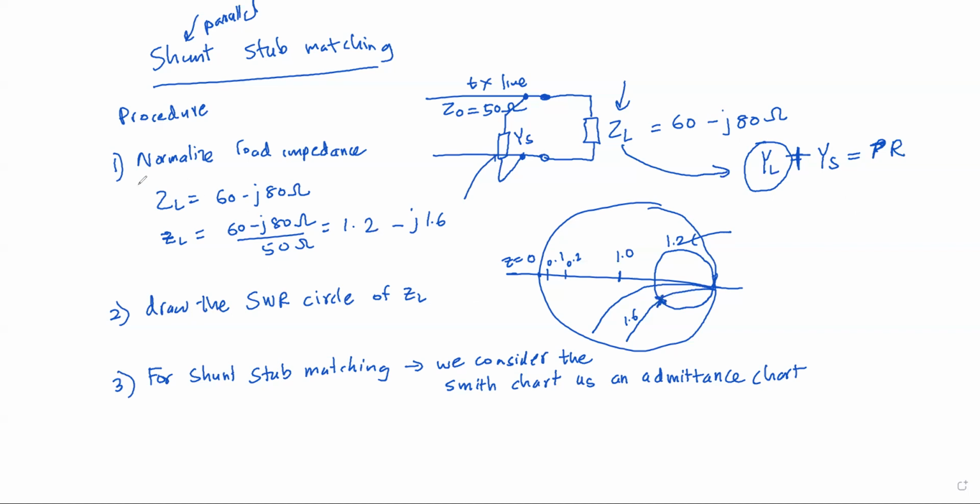So in the first step, you found the impedance value and you marked the impedance value in this chart, and this is the impedance value, right? In order for us to find the admittance value, we need to do something. How can we find the admittance value? What is the shortest method? If the impedance is here, we can take the magnitude, then take the 180 degrees shift, and draw a line across the 1.0 point.